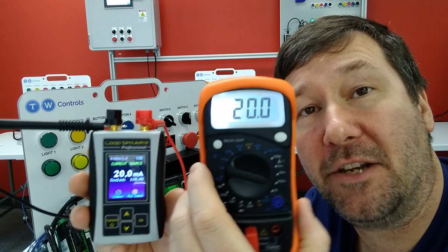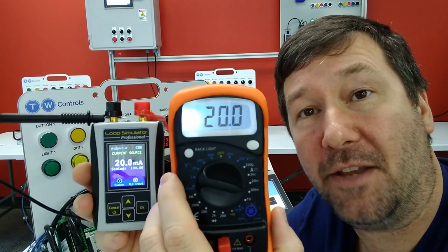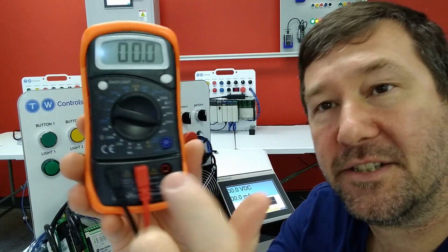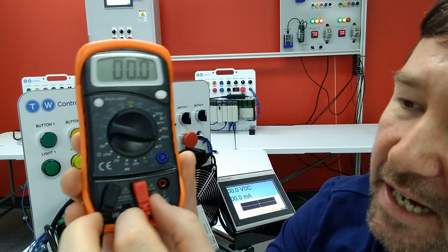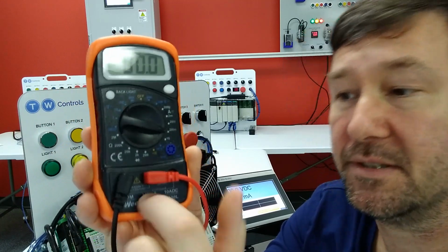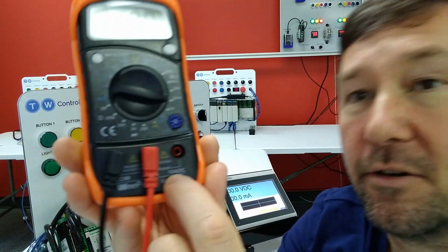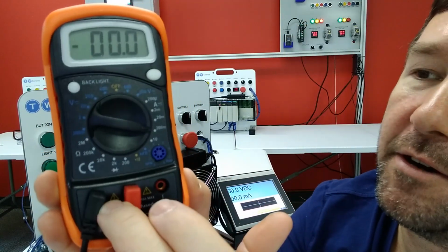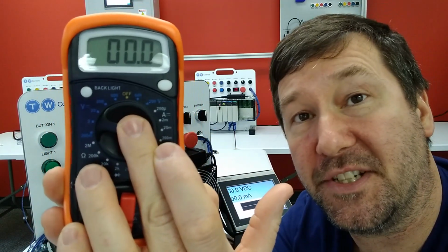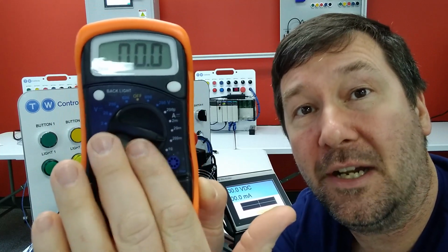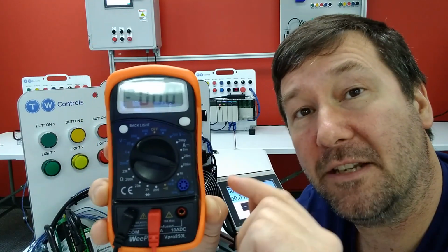If you get to this point and your meter is not showing what the ALP2 says, then double check the connections down here on your post, because every meter is going to be different. So make sure that it is milliamps. Like in this case, we could be over here on this 10 amp one, but that's not going to read milliamps. So verify that and verify your position. And if you still can't read the signal coming out of the SIM-ALP2, then check the fuse in your meter.